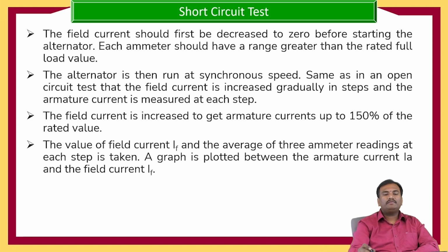And here the field current should be decreased to 0 before starting the alternator. In every step, the field current should be 0 before starting, and each ammeter should have a range greater than the rated full load value.